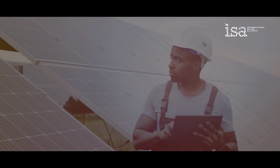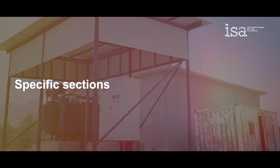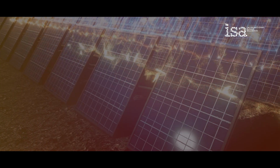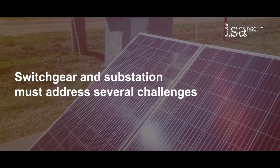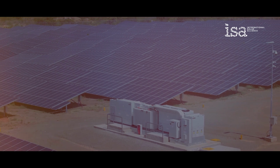For maintenance and repairs, switchgear allows specific sections of the solar plant to be safely isolated from the grid. This allows maintenance personnel to work without shutting down the entire plant, saving time and improving overall efficiency. To maximize efficiency, the design of the switchgear and substation must address several challenges unique to large-scale solar power.